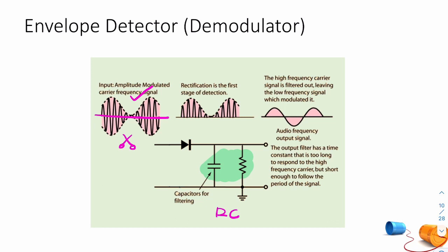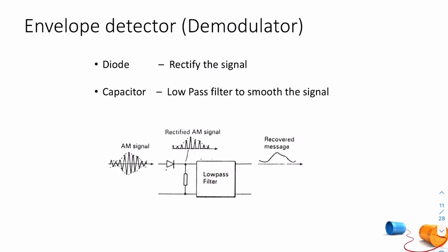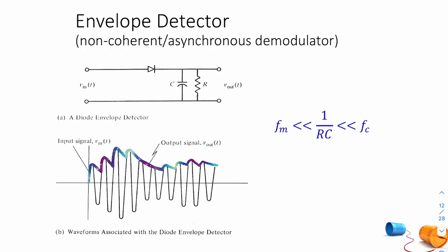So you see the demodulation circuit is really, really easy. Here what you have coming in is your AM signal, and what comes out from these two terminals is your message signal, or a version of your message signal. And all you need is a low-pass filter and a rectifier. That's your low-pass filter, and that's your rectifier. And that is what we're trying to recover. So again, you've got your rectifier and your low-pass filter.